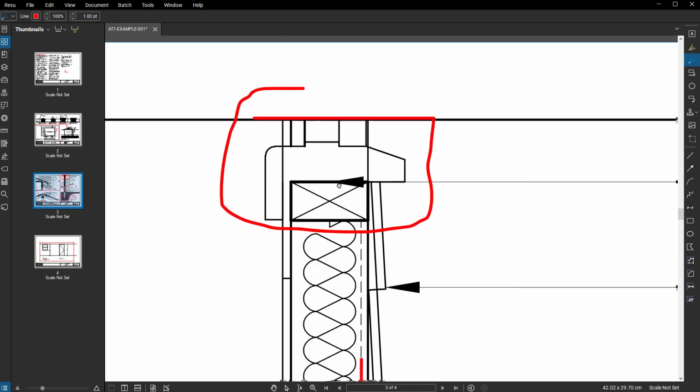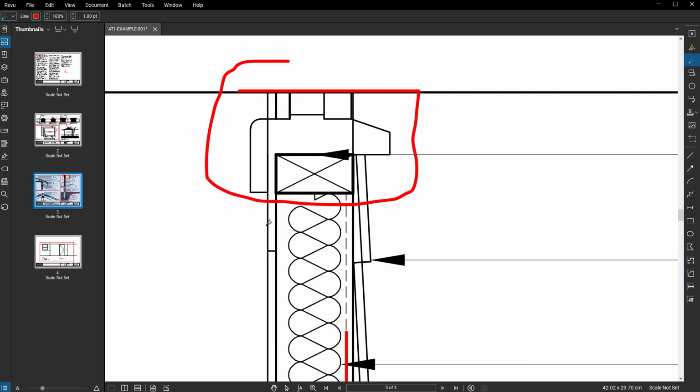In our essence here, I'm just going to eyeball this as best as I can, and the actual construction of the window frame, the window sill, how that fits with your bottom plate and your sill plate and your lintel and whatnot is going to be covered in your construction class. Here we're just sort of showing you how to actually draw this. So what you've got essentially is you've got your window framing on the inside. You've got the window sill, which sits somewhere around here with a bit of a profile, and then you'll have your glazing itself, and your glazing will probably be about here.